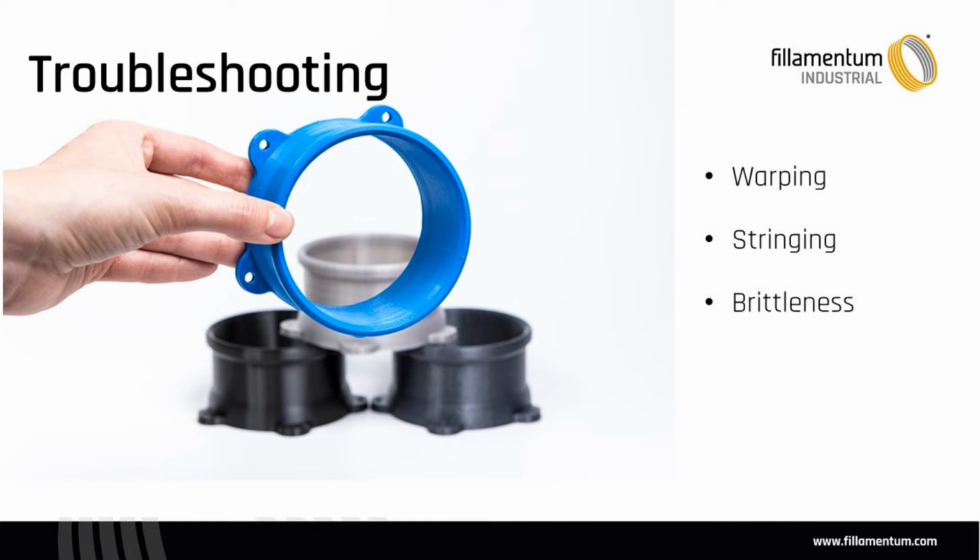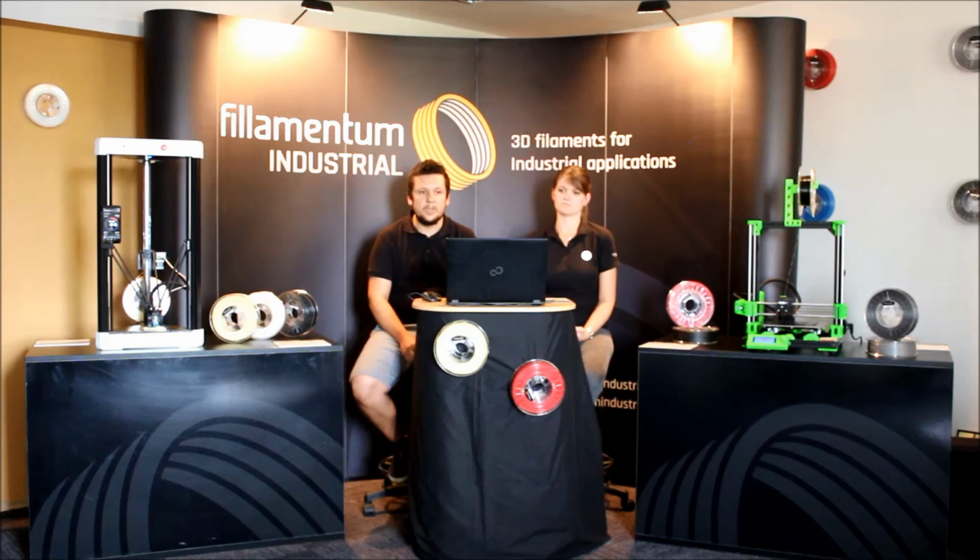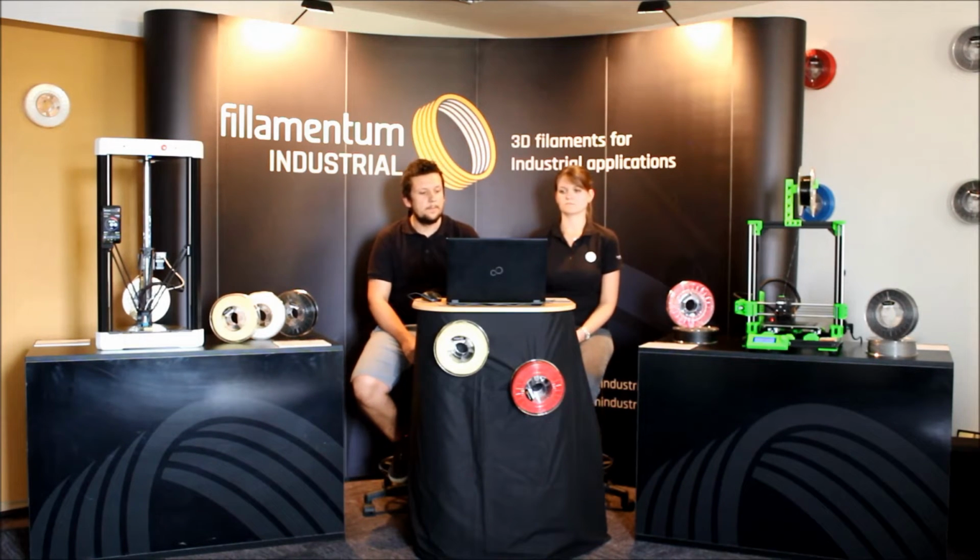And the third one is brittleness. That is mostly caused by too much airflow from the part cooling fan. When the speed of the part cooling fan is too high, the layers don't have enough time to cool down properly, and the material is brittle, so you can easily separate the layers by hand. So the printed part is not as strong as you want. So that's also important.